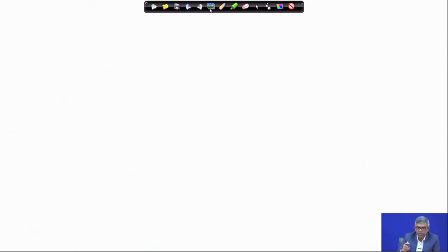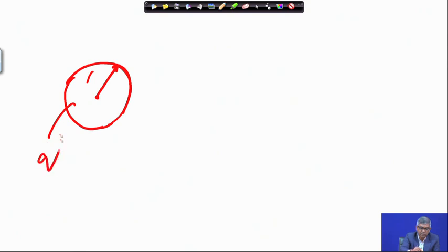So, as I have shown, for the annular footing, I can do this by applying the method of superposition. You can see it is given, outer radius of 8 meter and inner radius 6 meter. So, this is suppose 8 meter, and suppose I assume this entire area is loaded with intensity q, then at 5 meter depth delta sigma 5 I can find out.